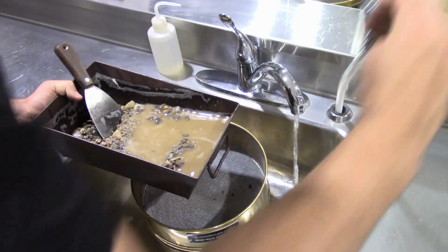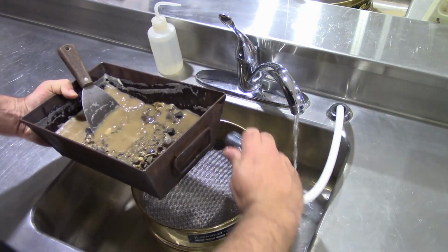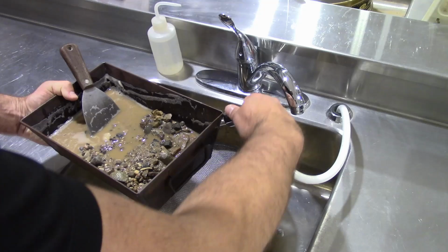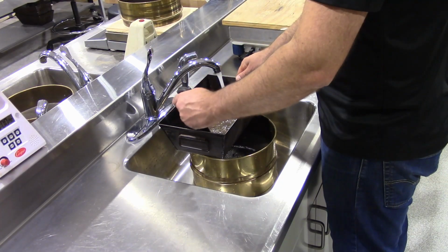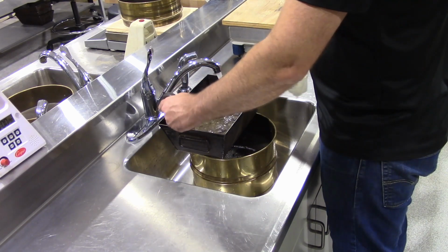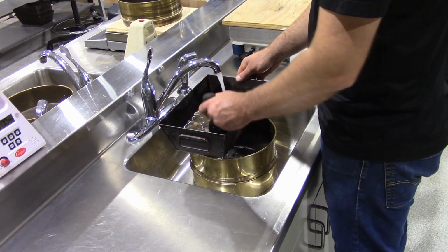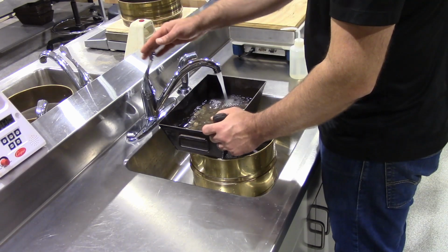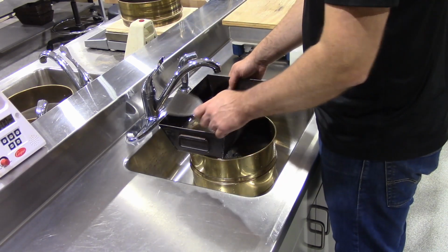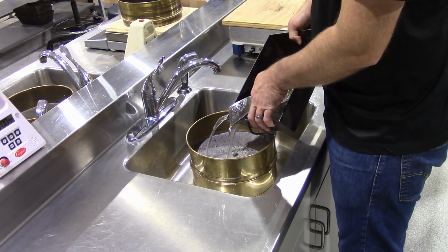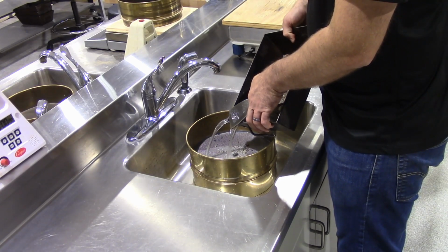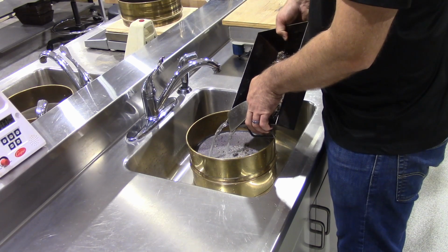Periodically wash the outside of the sample pan into the sieves as well. This helps ensure that no errant particles from inside the pan dirty the outer walls of the container or bowl. Be especially careful to not allow any water to be drained outside the sieves. To ensure this, make sure to keep the lower edge of whatever bowl or container you use over the sieve openings as well. It is very common for the surface tension of the water to cause the stream to cling to the edge of the pan when pouring.